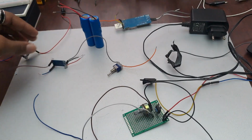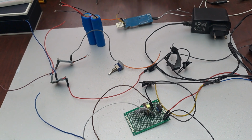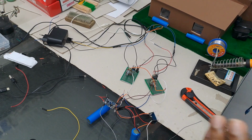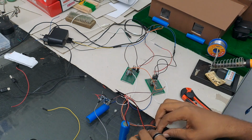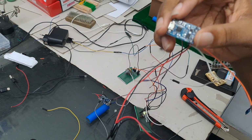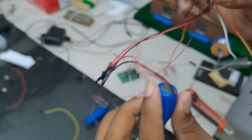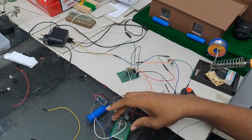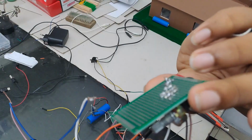So we have a 12-volt adapter which has 2 voltage regulator circuits that output 5 volts. Each of those voltage regulator circuits charge an individual battery, and then the output of those batteries from the charging module are connected in series and then fed to the Arduino, and the Arduino supplies power to every single other thing on the schematic. Now you can actually supply power to your LCD, your ESP01 Wi-Fi module, and your RFID card scanning module, all separate from your Arduino, and those would drain from there instead of draining from your Arduino.